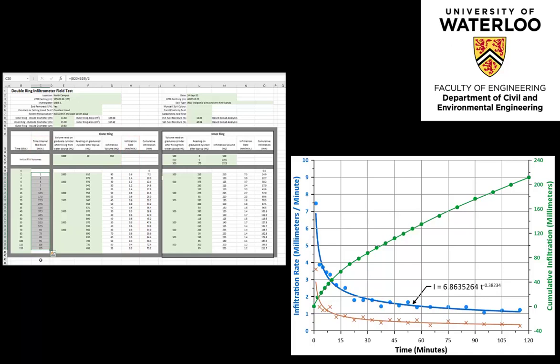If, however, the infiltration rate of the outer ring area remained above that of the inner ring area or crossed the curve of the inner ring area, these would be indications that the larger volumes of infiltrating water were contributing to transverse dispersion and that the flow field could not be idealized as readily as a one-dimensional flow field.